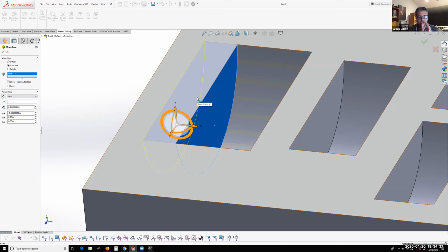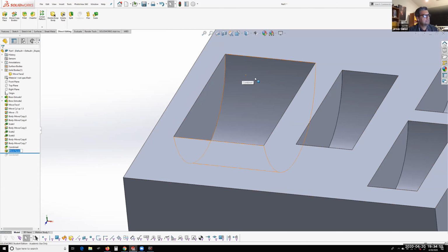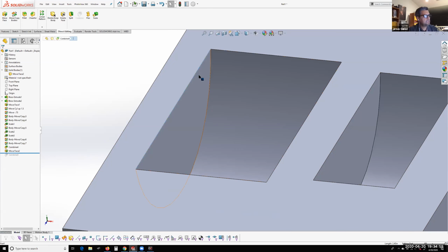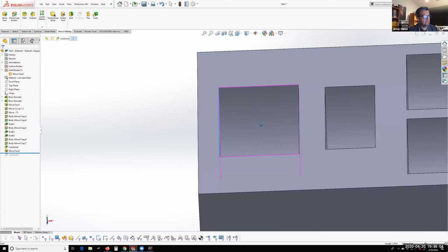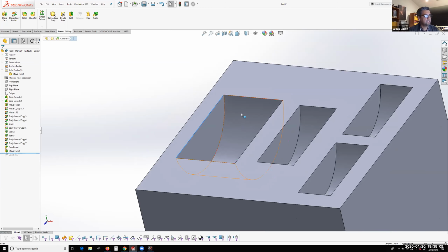So even though you only selected that one face, everything that is knit and tied to the edge of that face also goes along with it. So when I let go here and say okay, see how this face also got bigger and this one got reduced basically. So this moved over as well, so now I had this increase in size for that.